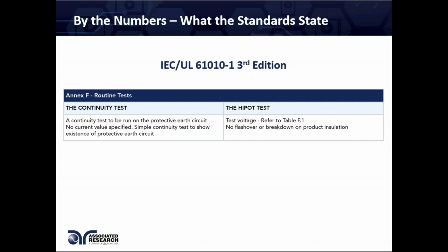if the design of your product meets the criteria and passes the requirements of the standard, you know that's how the ground of all your products is going to be designed. So you don't really need to perform a ground bond test once you move into production and start high volume production of your product, the design of which had already been approved by the agencies you were working with. If that is the case, most test standards do not require a ground bond test to be performed at end of line or end of production, in other words, on fully assembled products, for the very fact that their design has already passed the ground bond test. So all you need is a quick continuity check to make sure that the ground is still continuous.